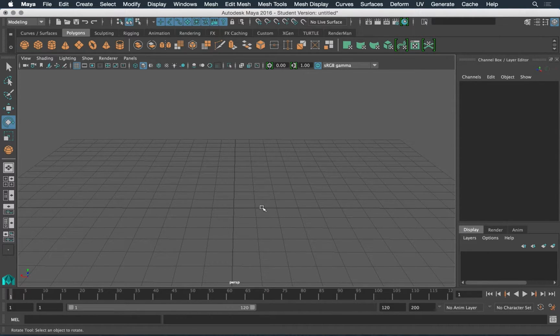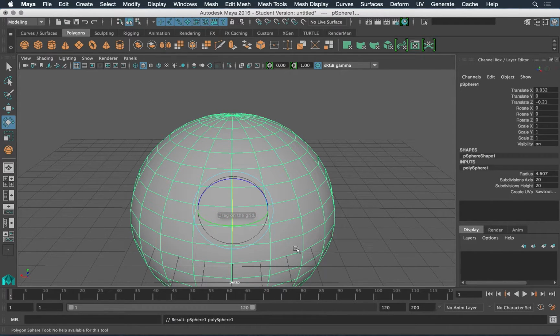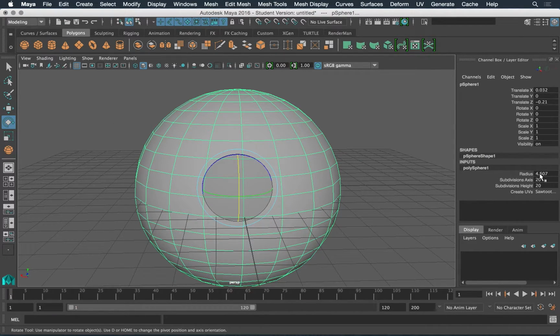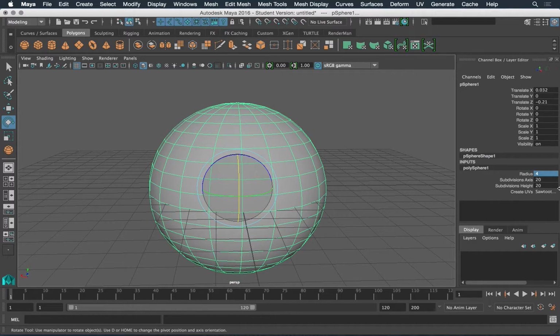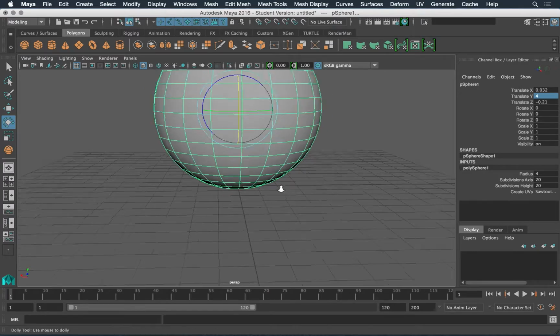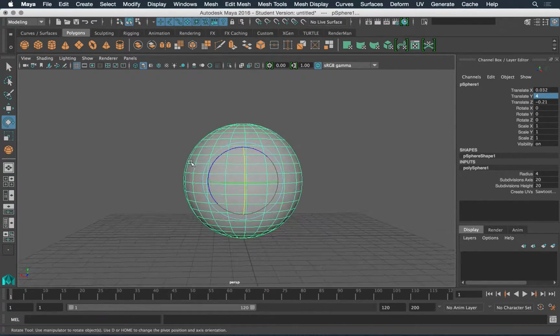The second is to make the sphere again. Drag it out. Again, I'm going to adjust the radius, so maybe I'll do 4 here since I was close to 4. And the height will also be 4, which is, again, that's the radius. So now it's sitting on the grid.